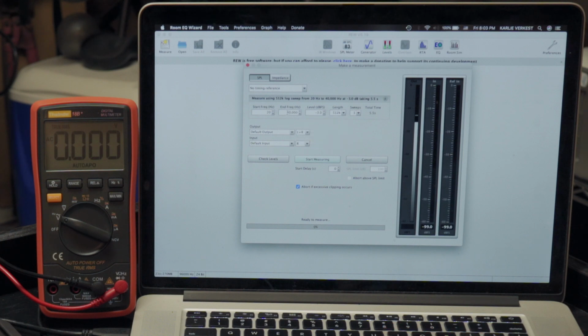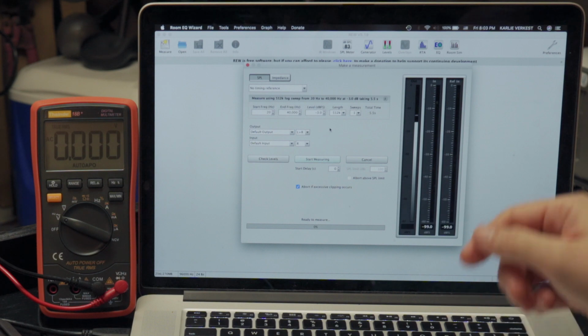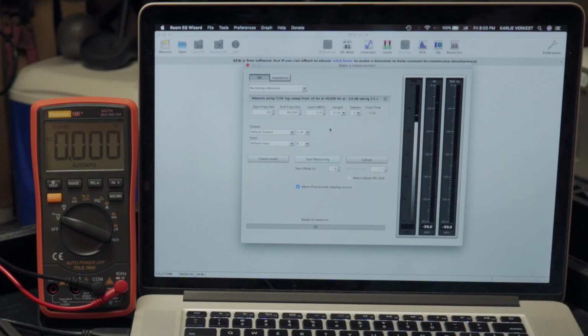The reason you want to sweep above the audible range is that it allows you to look at the harmonic distortion for lower frequencies higher up, because obviously second order, for instance, from your fundamental at 10K is going to be 20K, and second order for 20K is going to be 40K. And so this allows you to measure your harmonic distortion the higher you go. You can set your length however you want. This will change the measurement somewhat. This changes how long you will spend doing each sweep, right? And there's a little bit of level of detail there that we get into.